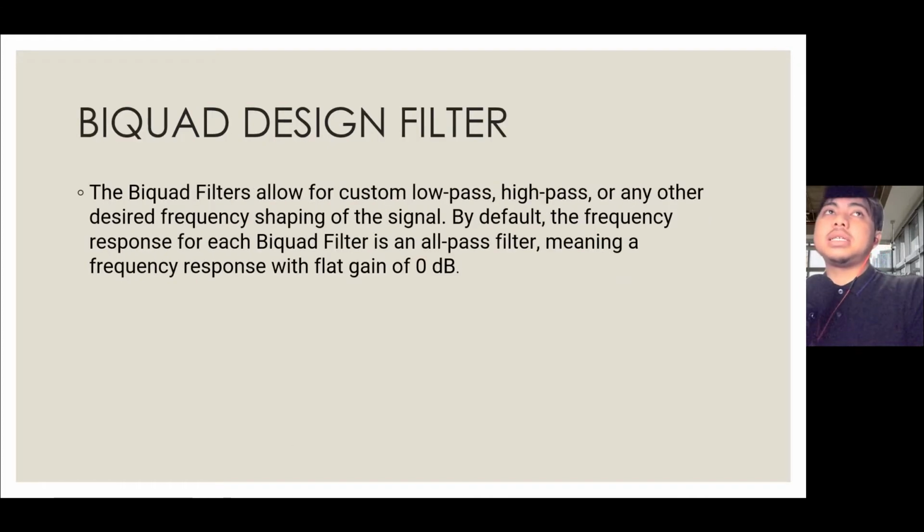So next is the biquad filter design. The biquad filters allow for custom low pass, high pass, or any other desired frequency shaping of the signal. By default, the frequency response for each biquad filter is an all pass filter, meaning a frequency response with a flat gain of 0 dB.